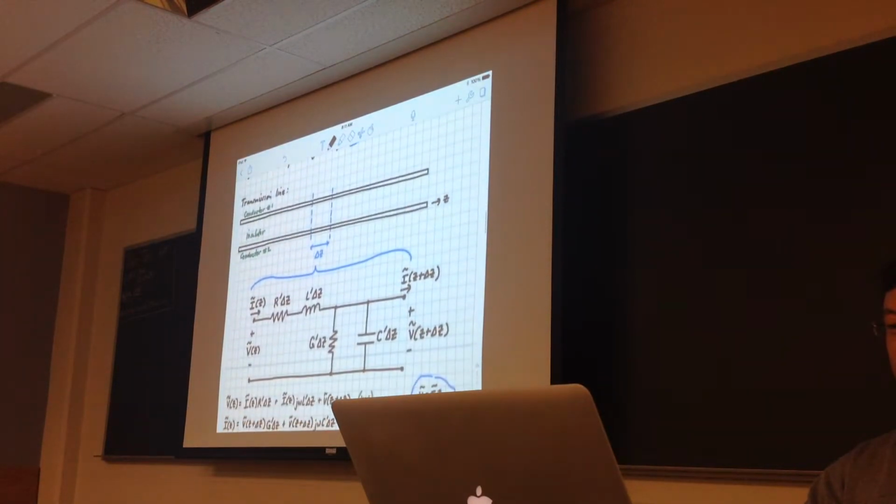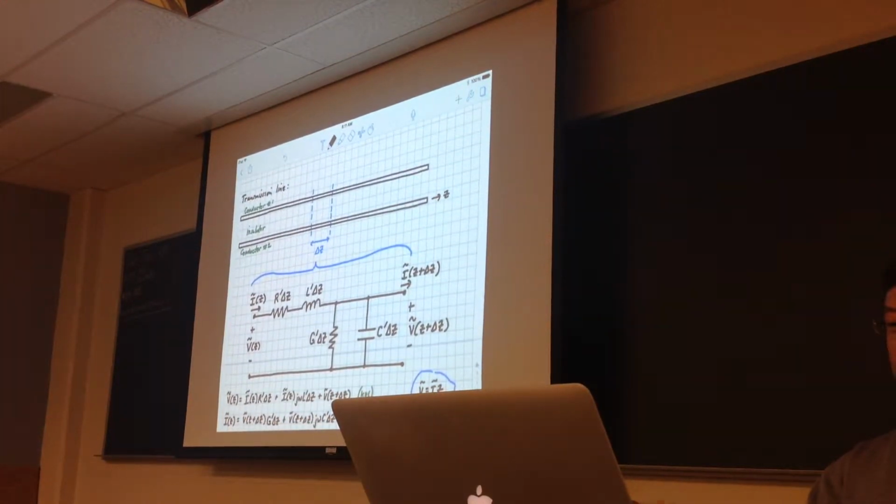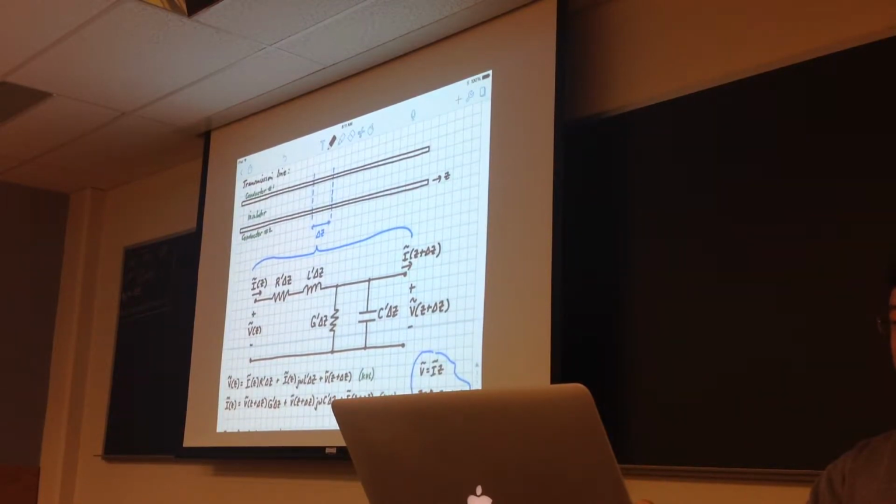Here's our transmission line model. So we would say that the transmission line is lossless if this resistance per unit length is 0. It's an ideal case where your conductor has no resistance per unit length. It's made out of something better than gold or something better than copper, an idealized conductor. Okay? R prime is equal to 0.